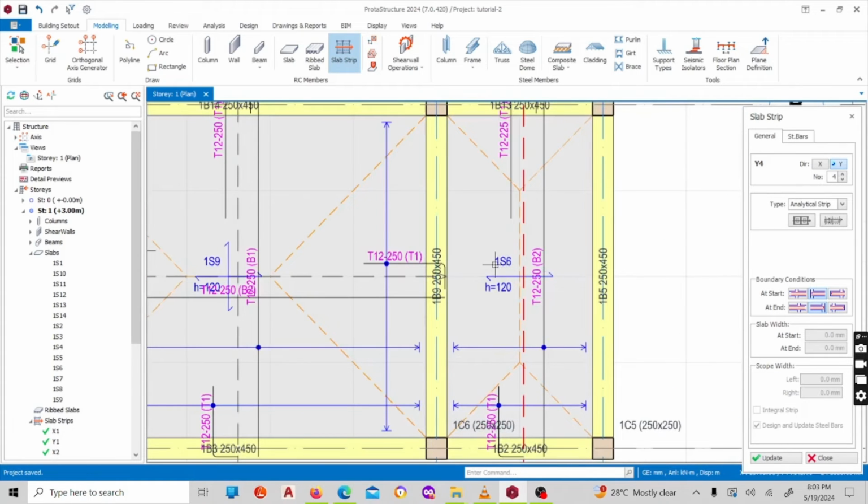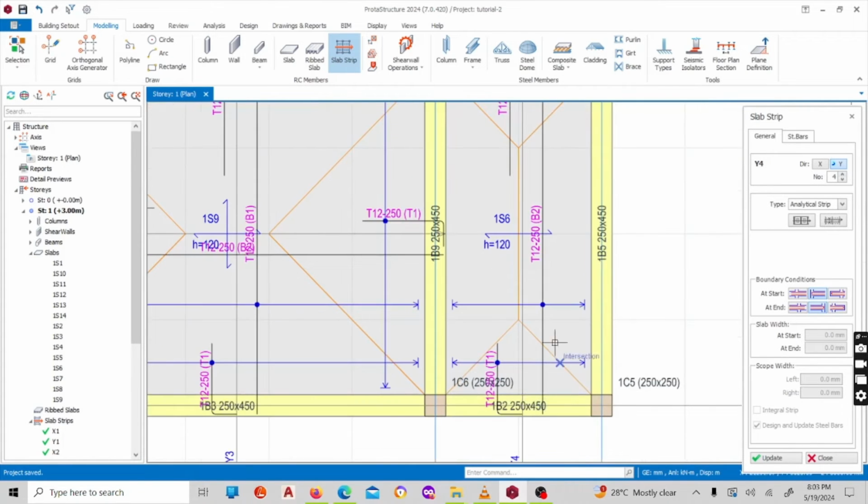You can see this, it was telling you the loads are spanning in this direction. That's why you put it on y, because these rebars will go with this line here. This array shows you how the rebars are going to be arranged in this direction as well as in this direction.